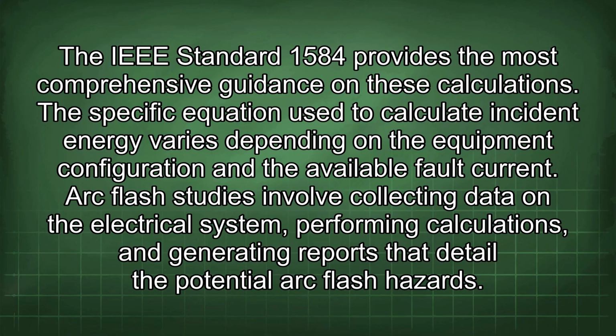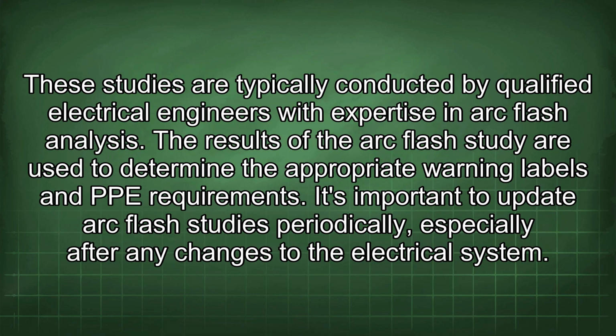Arc flash studies involve collecting data on the electrical system, performing calculations, and generating reports that detail the potential arc flash hazards. These studies are typically conducted by qualified electrical engineers with expertise in arc flash analysis. The results of the arc flash study are used to determine the appropriate warning labels and PPE requirements.